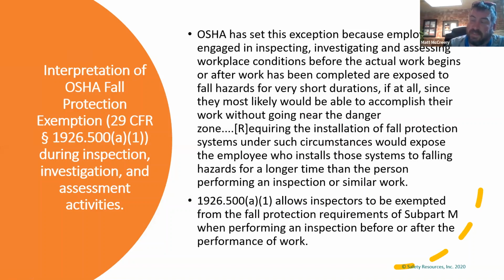I would say it comes into play about 3 or 4 times a year throughout our firm, because Betty next door will take a picture of someone out on a roof without fall protection. But then when OSHA shows up, or when OSHA asks us why it was happening, we can oftentimes, hopefully, if everything's going right, point towards this exemption and say, hey, listen, there was no work ongoing. They were just up there to inspect. I mean, obviously you want to be truthful with that. So we wouldn't say that if there was actually work ongoing, but it does come up quite often.